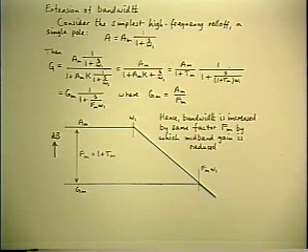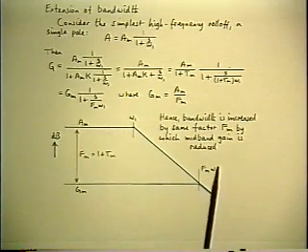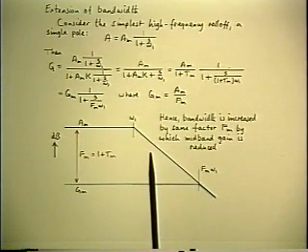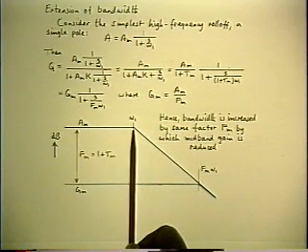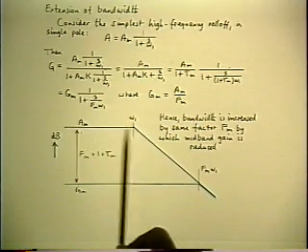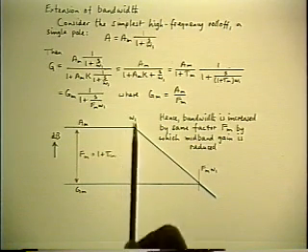Notice this is a much better deal nowadays than it used to be, because we can start out with a lot more gain available to be traded with modern ICs. It isn't quite that good, though, because you also start out with a lot less bandwidth, because the pole of a 741 is around 10 hertz. So it's a good thing you got a lot of gain to throw away.